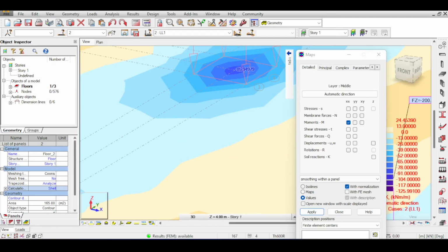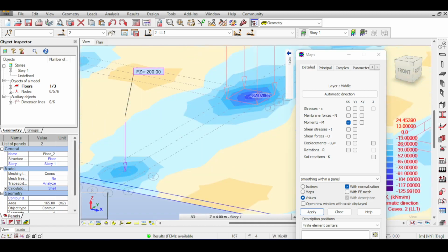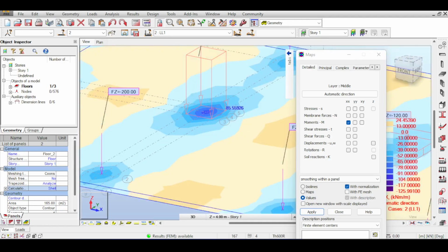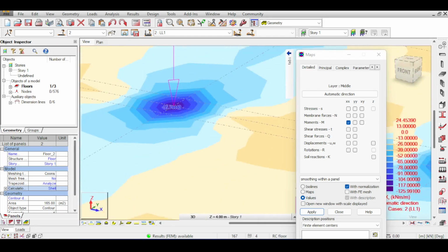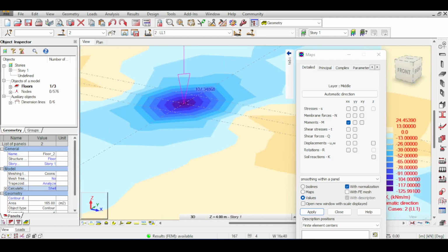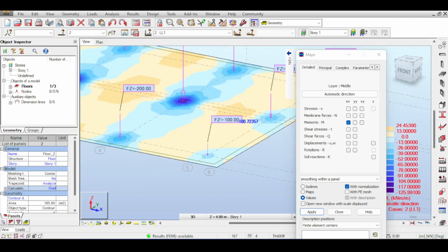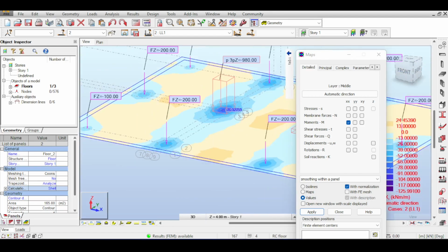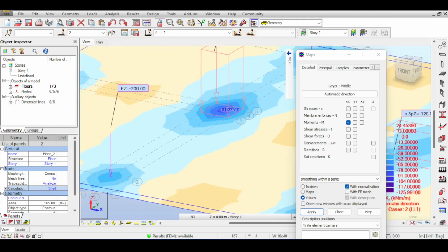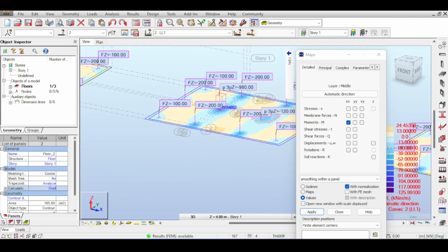So if you calculate this, 85 divided by 118 multiplied by 100%, what you get is that the moment under a column that takes the column size into account is 72% as large as the moment under the column that uses a point load, because a point load is like a needle, whereas a distributed load is the correct way. So this is more accurate, to be honest. And you can see that this is 81, 83 something, so it's like 70%. There is a reduction of 28% here.